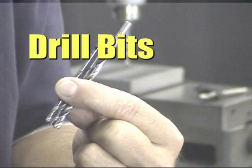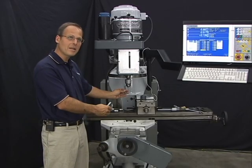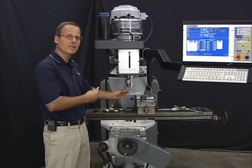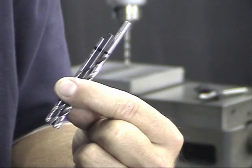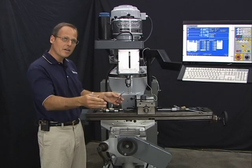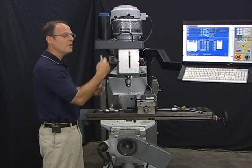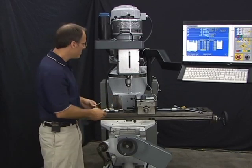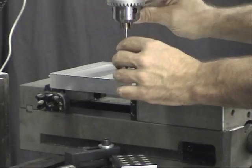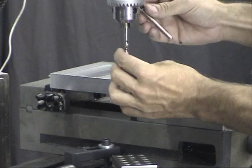If I can remove one drill bit out of a drill chuck and put another bit back in at approximately the same height, then that drill bit has the same tool height offset as the one I took out. You could actually have a group of drills. Each drill would be tool 3, 4, 5, 6, but they're all going to have the exact same height offset value. And when the control comes up and asks you for a tool change, you're not actually taking the drill chuck out, you're just sliding the new drill bit in at approximately the same length as the one you took out. Hitting cycle start and away you go.